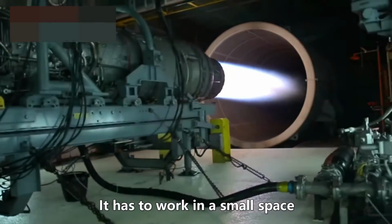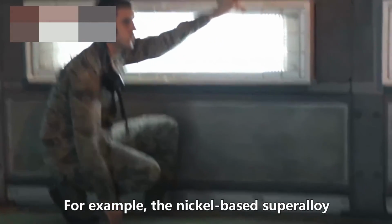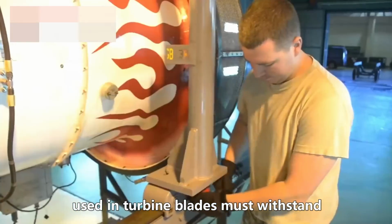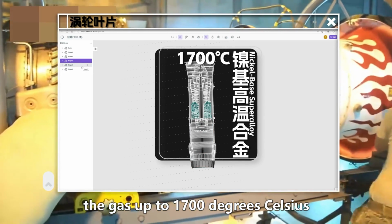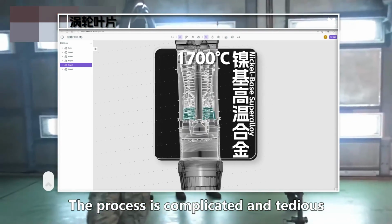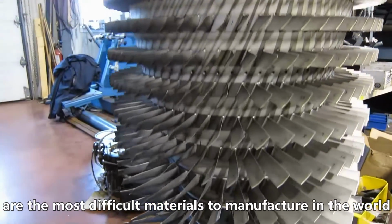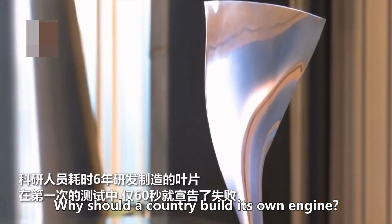They have to work in a small space under high temperature, high pressure, high speed, and high load in severe conditions. For example, nickel-based superalloy used in turbine blades must withstand gas up to 1,700 degrees Celsius. The process is complicated and tedious, and the cooling structure and coating are among the most difficult to manufacture in the world.